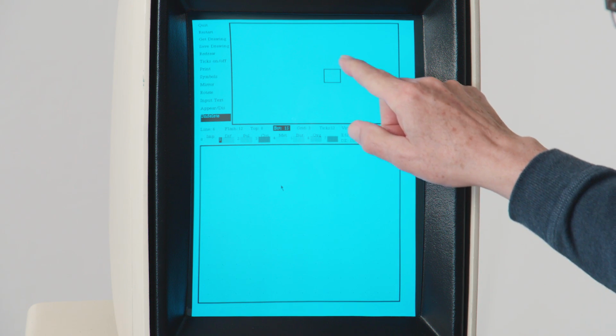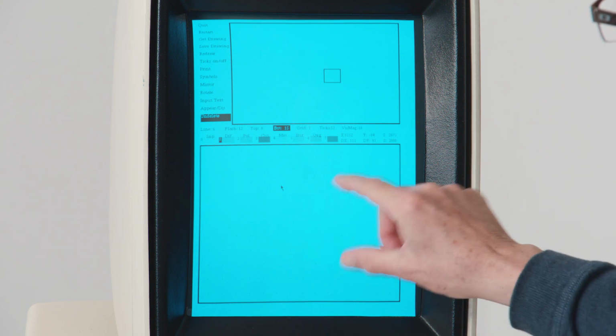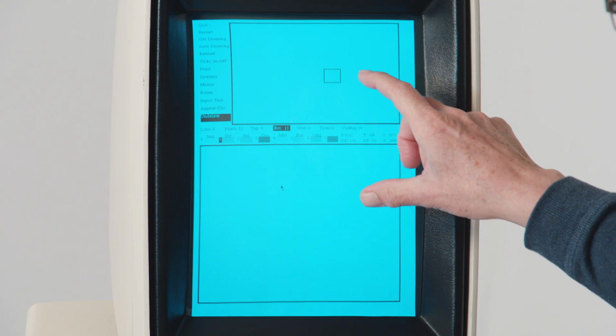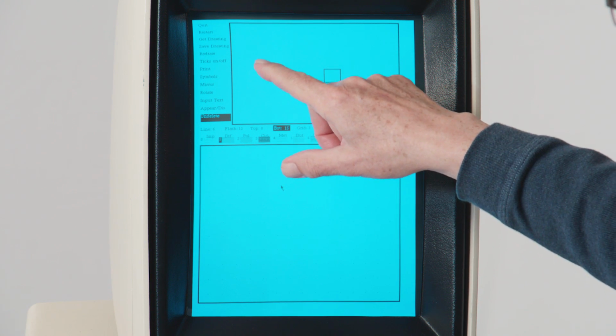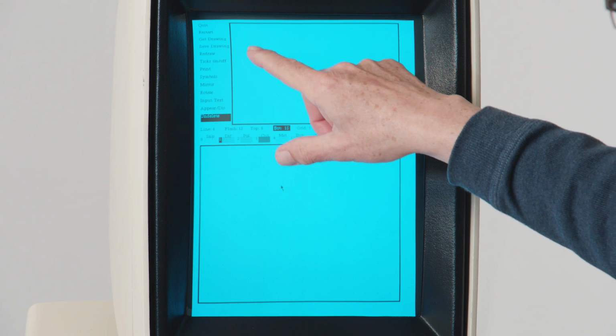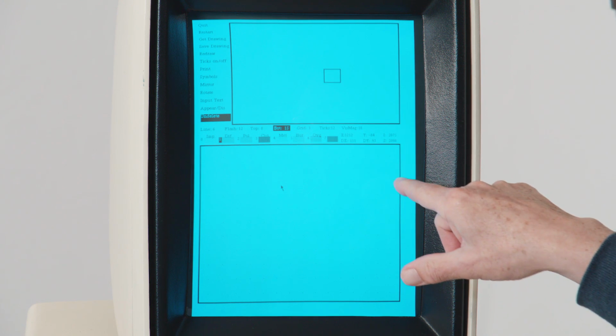This small rectangle in the middle of the upper window outlines the portion of the chip that is actually shown in the lower window. You can in fact use the windows interchangeably, and you can draw lines or other structures between the windows. For example, you could start a line that you wanted to cross the chip in the upper window and then complete it by clicking in the bottom window.